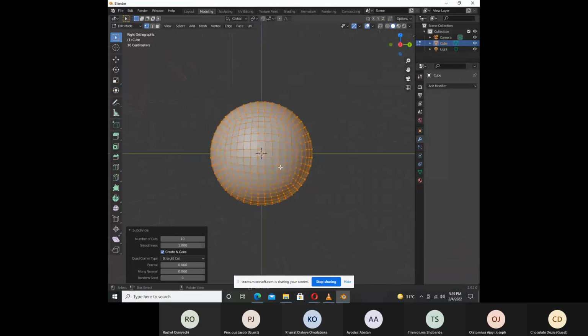We'll be working on this knight piece in parts. Model the head differently from the neck segment and then the lower part of the neck. All right. So we'll need 3 of these spherical cubes which we have here now. So we'll go back into object mode and duplicate this.